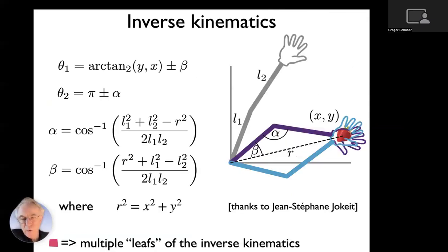That gives rise to a problem that is a problem in robotics, but actually not in human movement. Many of these equations will invert harmonic functions, sine, cosine, and tangent functions, and as you know, these functions are not monotonic, so they often have two solutions for almost all cases, except for these singular points where you just touch, but anywhere else.